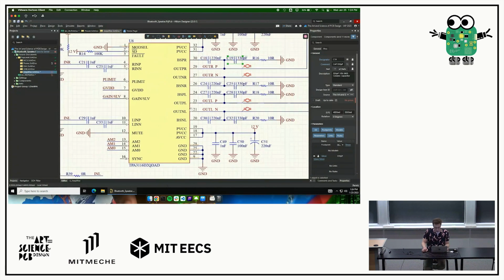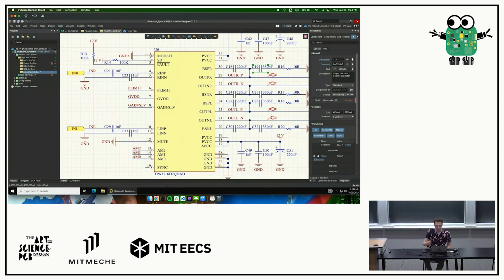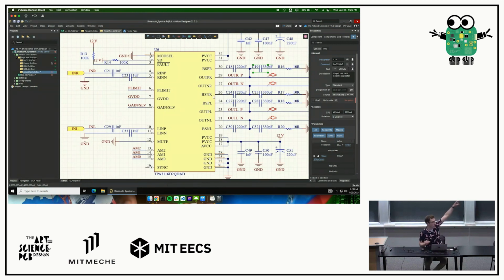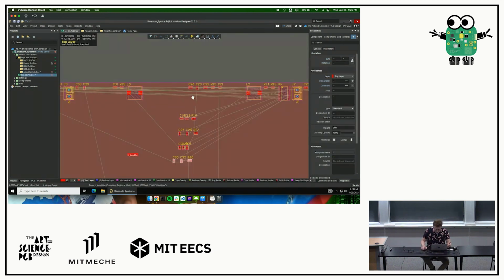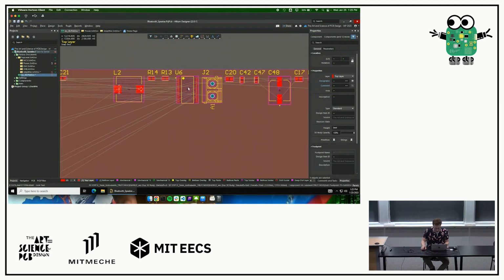And then let's go back and take a look at our amplifier schematic. What do we notice about the numbers over here as they come back around? They seem to have some kind of order to them, right? We start at pin 1 over here, and then 2, 3, 4, 5, we loop back around. And there's some weird stuff that happens over here, but we go 16, and then back up the side, 17, 18, 19, 20, 21, and so on. This is because when we label the pin numbers on parts, we usually start in the top corner and then go around the side. And we can actually see that inside of the part itself.